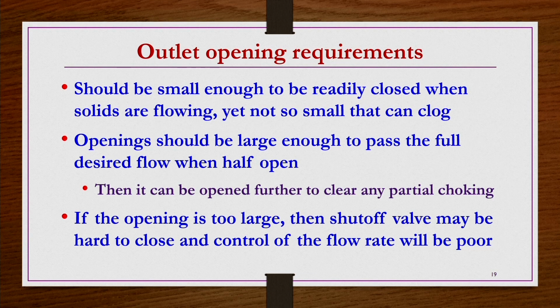If you have too big an opening and materials are coming in tens of kgs per second or something like that, that is going to affect the subsequent process. So, you cannot close it immediately. So, you cannot afford to have a very large opening. So, it should be optimum. It should not be so small that clogging takes place. It should not be so large that closing the wall becomes very difficult, or by the time you close the wall, a lot of material is flowing out. Those things should not be there. It should be very optimum. That is what you expect of the outlet opening requirements.